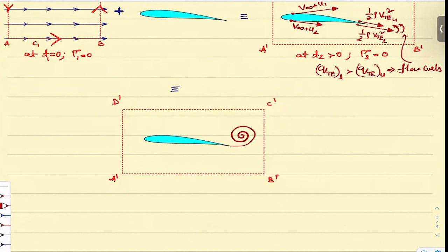Do that, everybody. So it is curling like this. It created one vortex. Once the fluid reaches this side, it will start to curl from the lower surface to the upper surface. So from the beginning, this is the first vortex that is formed. It's called the starting vortex.